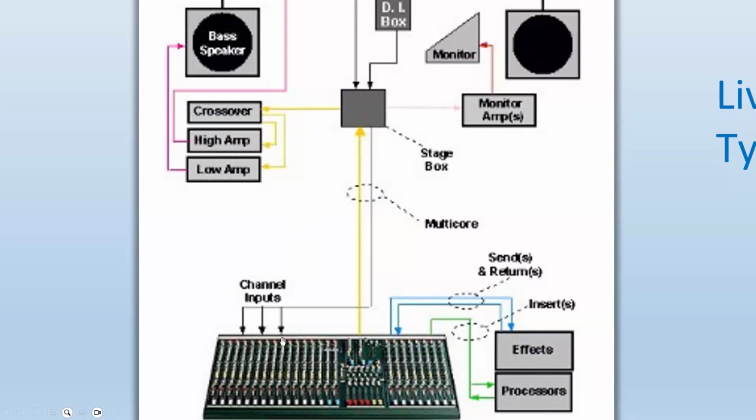So the inputs of the mixing board are in the range of more or less about 600 ohms, sometimes 150, 300 ohms. So anywhere from 150 to 300 ohms to 600 ohms. Big spread, right? Well, that's what it is, but 600 ohms is quite common, more than others.